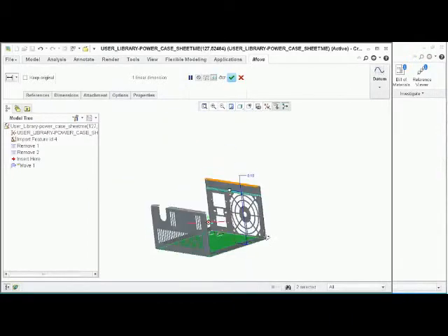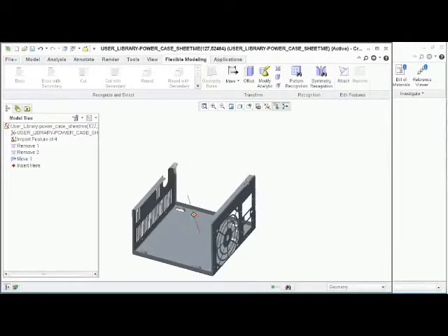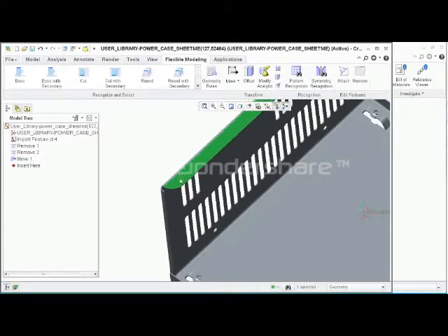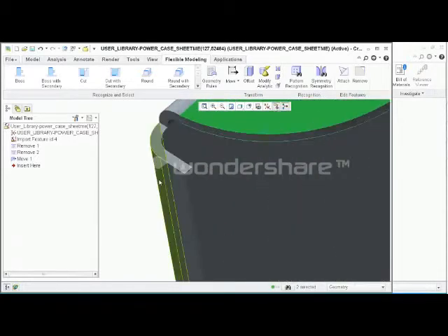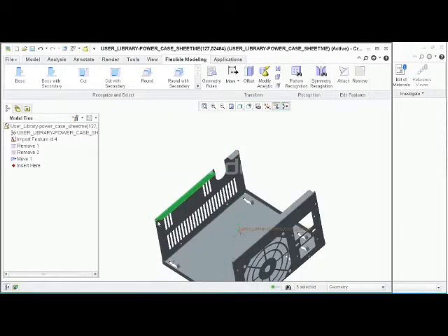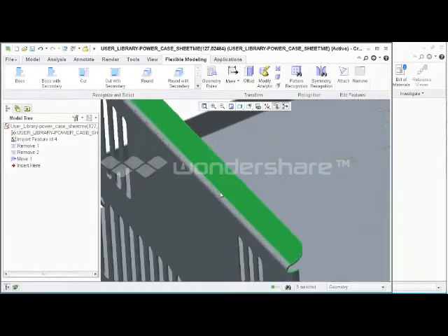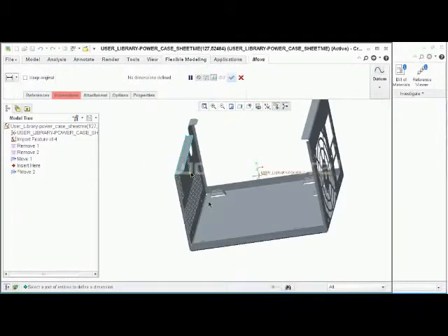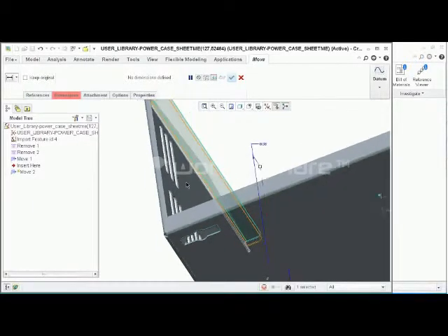Same thing on these other two walls or these other two flanges. Very quickly here, I'm going to grab the corresponding sets of surfaces here, this one and this one. Now, I could have done this all at once. I like to do it piecemeal just so it's easy later on to make future changes. So those are the three surfaces I physically want to move. So again, move with dimension. And I want to, again, dimension from the bottom to this surface right here. There's our 0.08 again. This is going to be 0.1. Again, we raise the height of that.